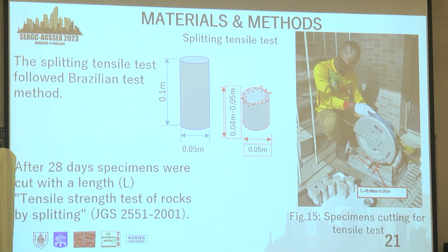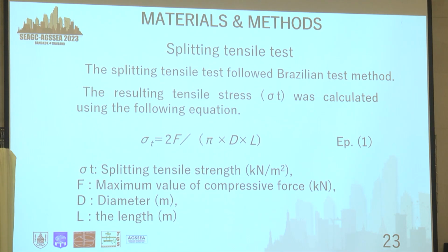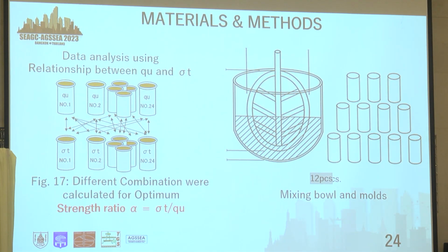From there, we directly apply the load using the standard compression test machine. Based on the formula, we calculate and obtain the splitting tensile strength of each specimen.